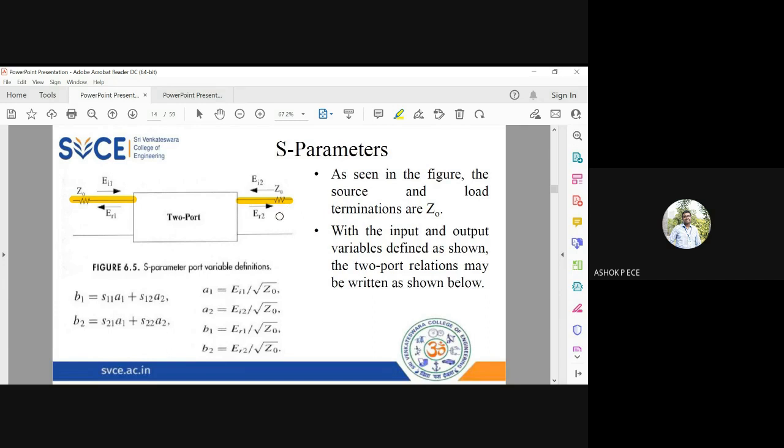You may ask a question. I was telling everything in terms of power. Why am I suddenly bringing voltage here? Power is finally got by multiplying V and I. So in analysis, we'll do everything with respect to voltage and current. Finally, we'll convert everything into power. So you remember in transmission line, whenever you see Z naught, it means perfectly matched or it is perfect termination.